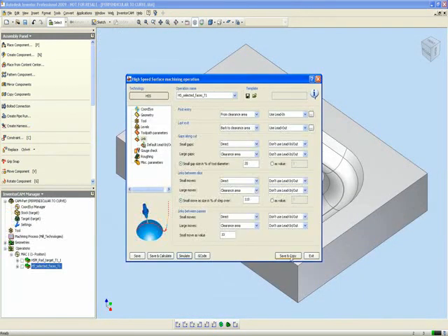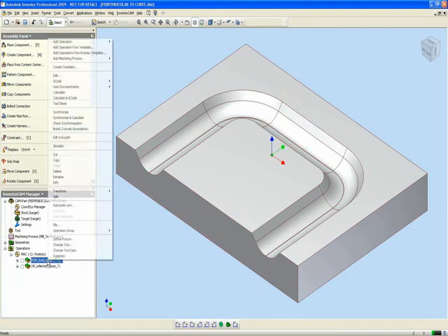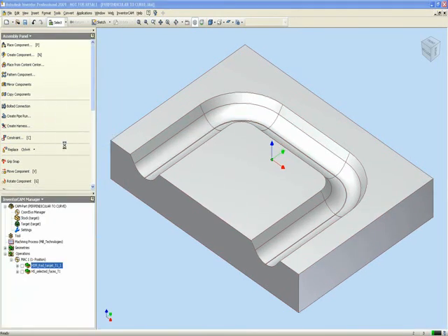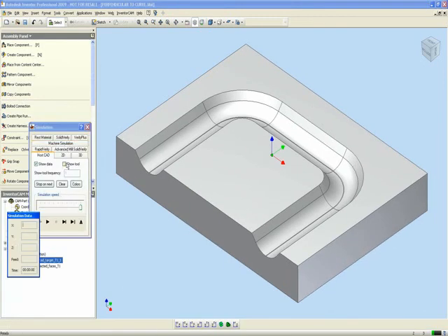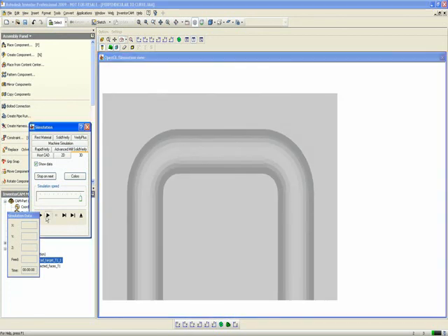Now, if I were to do this using HSM, which I can, you'll take a look at the simulation, and instead of getting that straight back and forth movement, what happens here is that the tool starts off going back and forth according to the center, but as it's moving away from the center point, it's always pointing towards the center, therefore starting to curve away on the surface itself.